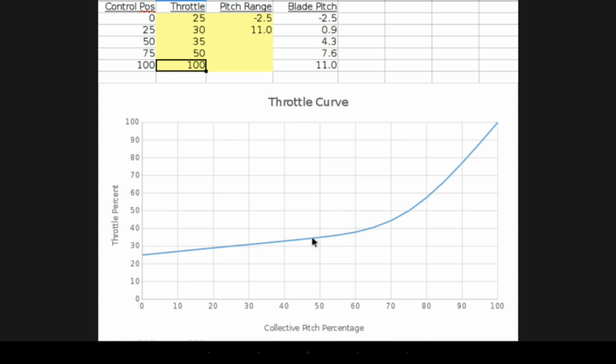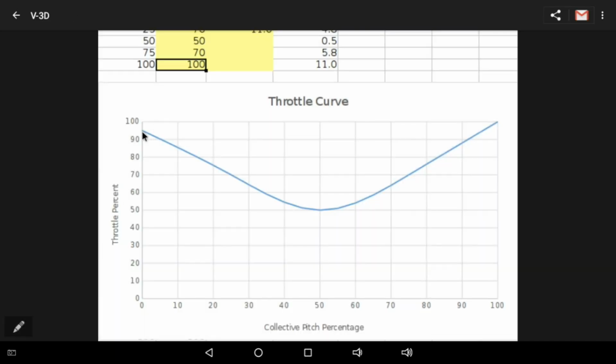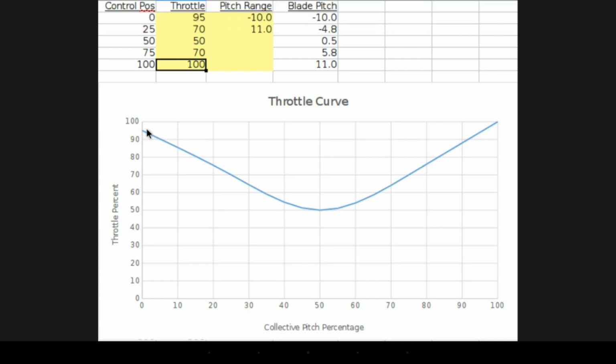So that's the nice thing about the new 5-point curve. It can be infinitely adjusted just by moving those 5 points. And the spline smoothing can make curves, let's go back to the V throttle curve. If you want, the spline smoothing can make a V throttle curve that would be fairly flat at the top end for an electric motor and fall very quickly to the V point, go back up to the 75% point, and then flatten off again for the rest of the way to 100%, just by moving the 75 and the 25 points on the curve.